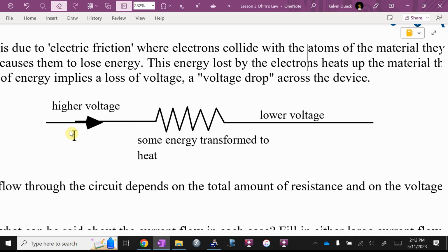Okay, let's suppose you had a voltmeter, and right here you measured 8 volts, and then here you measured 3 volts. Fahim, how many volts did you lose going through the resistor? Be obvious. Yeah, and you could write -5, but because we know resistors are always a voltage drop, we're lazy. We don't label it with a negative. You lost voltage. What that means is every coulomb of charge that goes through there gives up 5 joules of energy, 5 joules per coulomb. And we can use that energy for whatever, depending on the device.